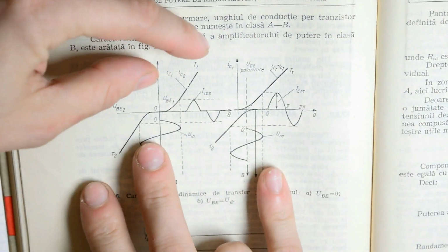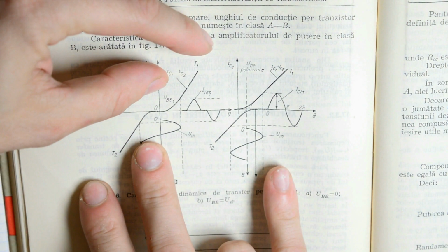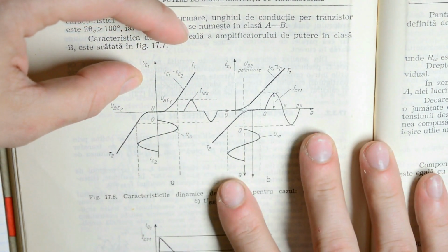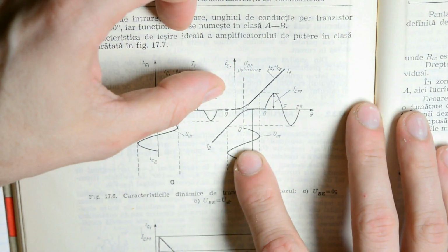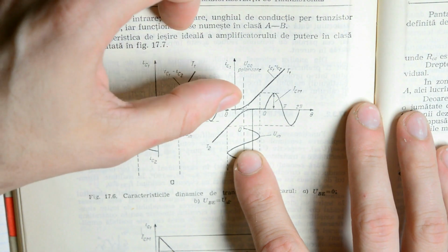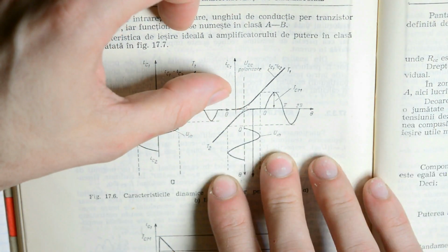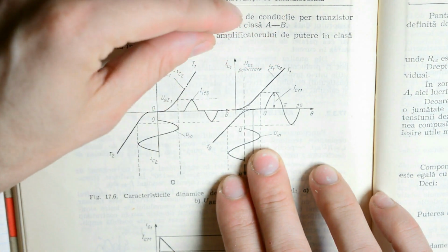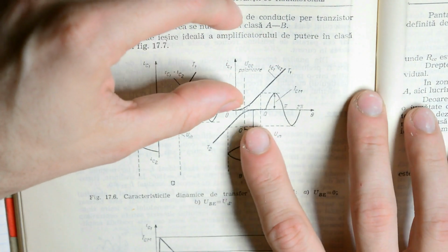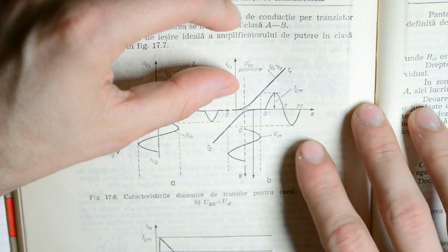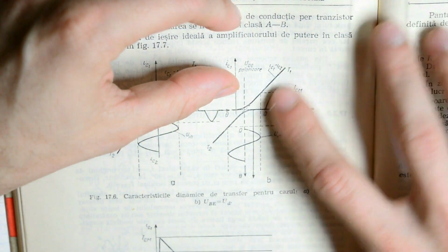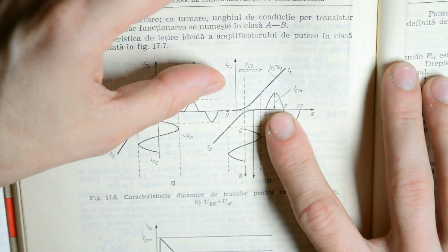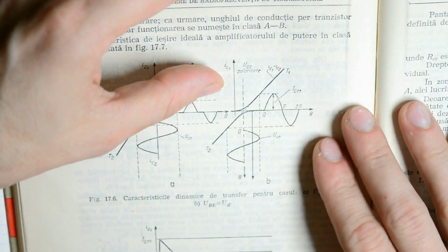Basically, you take these two operating curves of the transistors and you overlap them a bit. And you get something like this. Your input signal, when you are working with very small signals, is amplified by both transistors, and only when you have large voltage deviations are you being amplified by only a single transistor. By having this overlapping, the gain factor of your amplifier becomes linear, since the sum of these two exponential curves can be approximated to a linear amplification factor.